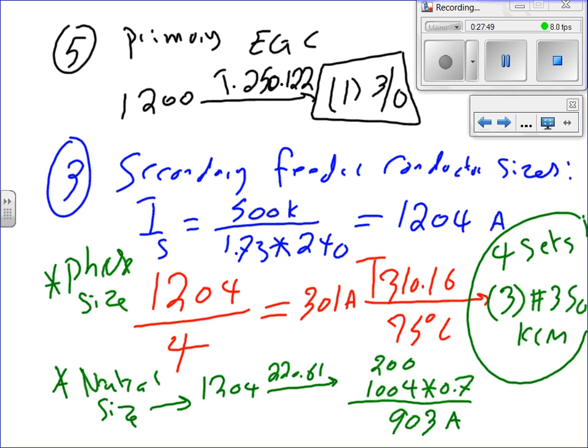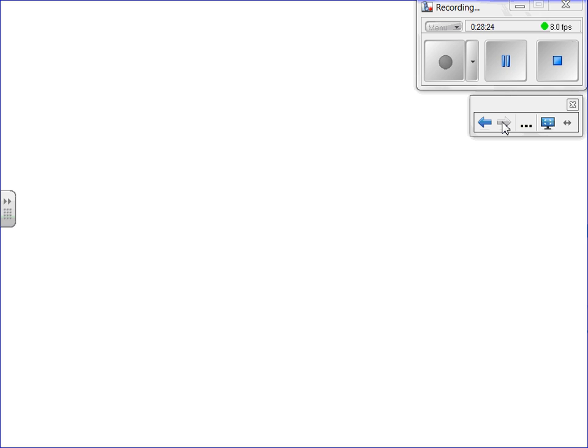Okay, so can I shift to the next one, guys? 1004? 1004, yes. Okay, cool. Questions? So then you're going to downsize it? We're downsizing it. It's 903 in each one. We're going to parallel them 4, divide by 4, comes to 226. So should I move? Yep. Okay, so we move to the second. We're still sizing 3, and we're still doing the neutral.